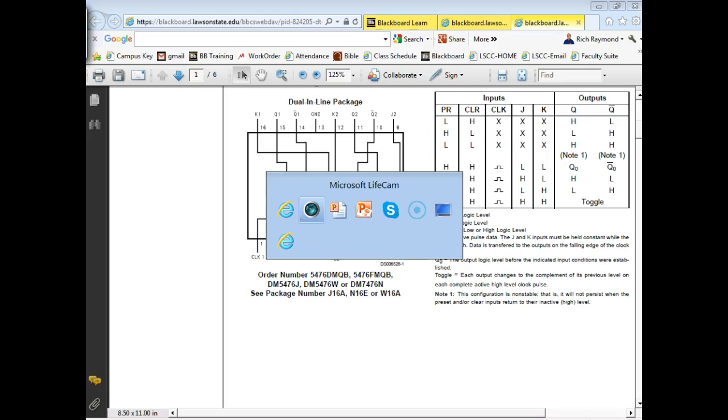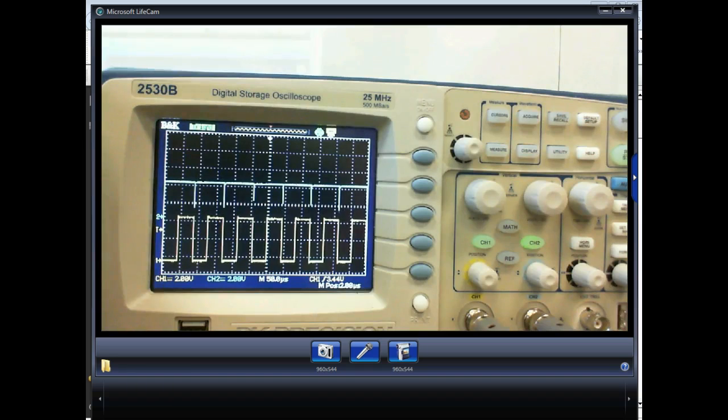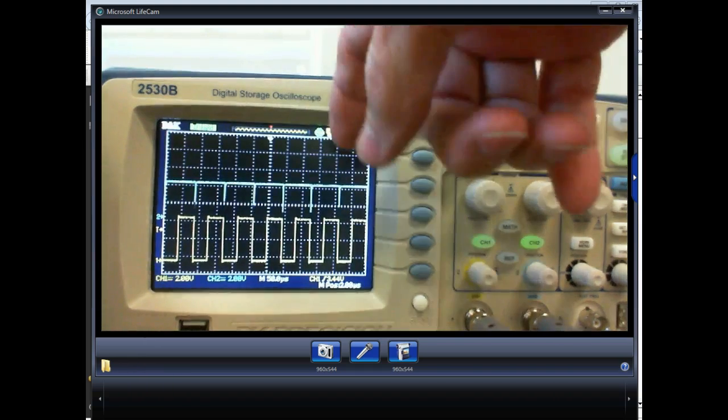So that would be this basic circuit that I've got right here. Now, whether you use an OR gate or an AND gate all depends on what the circuit is, what the trigger circuit is looking for. So this is an OR gate, and it gives me a negative-going pulse.